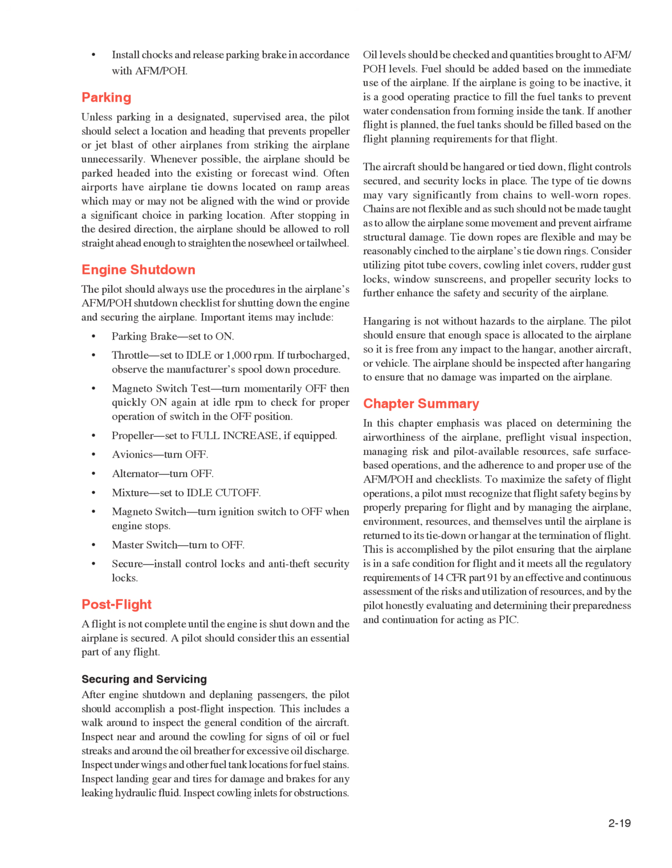Post-flight: a flight is not complete until the engine is shut down and the airplane is secured. A pilot should consider this an essential part of any flight. Securing and servicing: after engine shutdown and deplaning passengers, the pilot should accomplish a post-flight inspection. This includes a walk around to inspect the general condition of the aircraft.